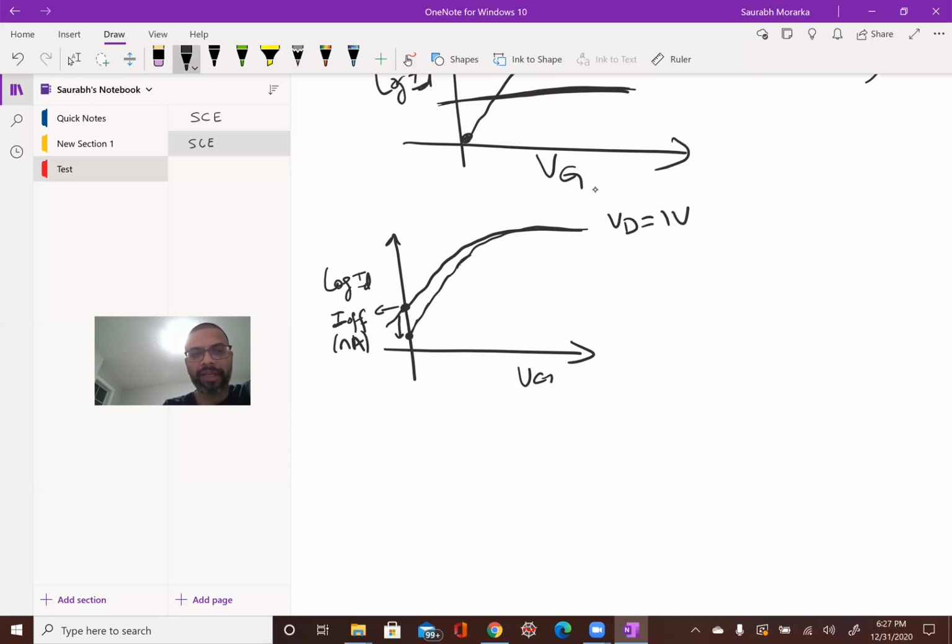And there is another case that he can do, which is, let's say the short channel effects cannot be improved. In that case, he can shift this curve laterally using what is called a work function, or the metal gate barrier profile, right? So if this thing is shifted, the curve shifts laterally.